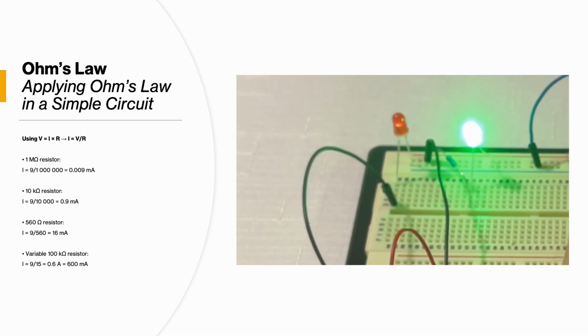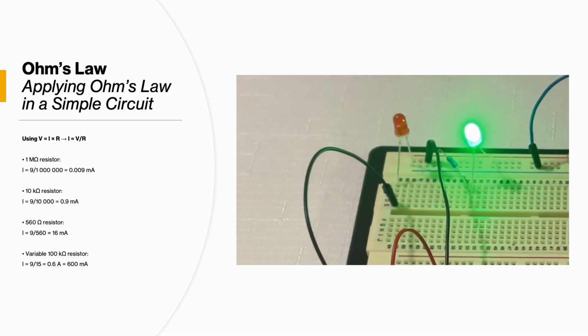As soon as the battery is connected, there's a bright flash from the inrush of current, then the LED dims as its junction is damaged. We zoom in to see the faint, unstable light from the partially failed LED before it finally burns out. This demonstrates how too little resistance allows excessive current and leads to component failure.